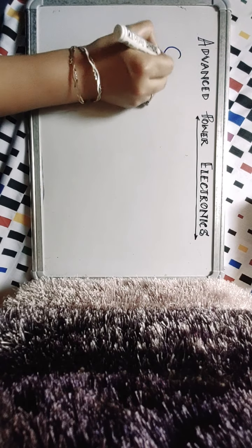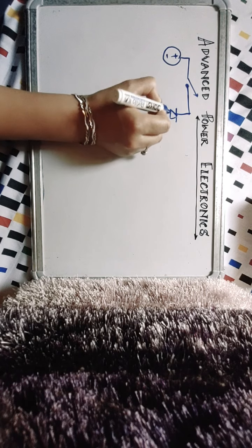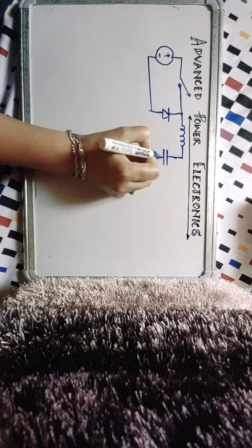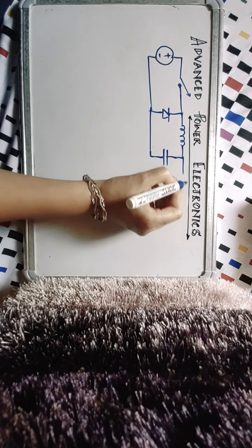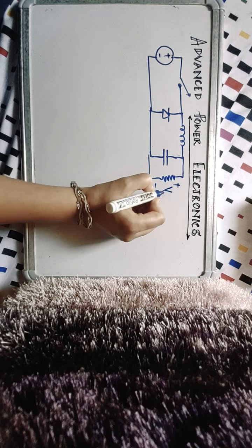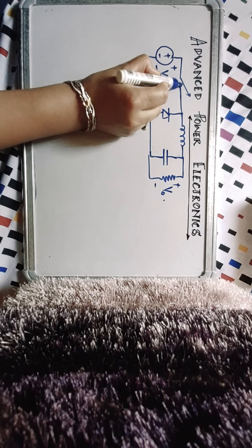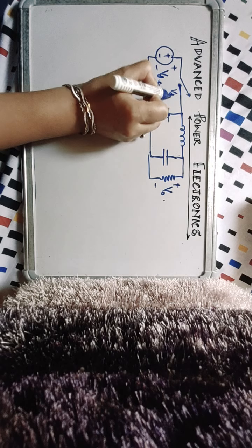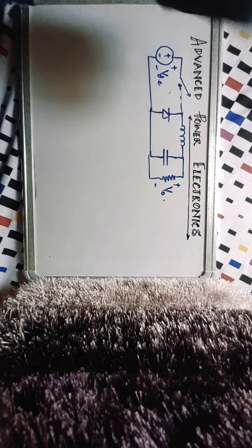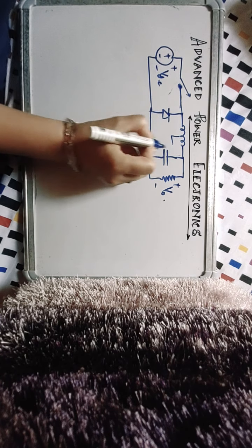So your buck converter has two very interesting components. Generally, not necessarily always, but usually you have them when your applications are those of power supplies where you want a regulated output. That is your L and C. So you have a load. The load will be defined by the user, what load will be placed on your converter. The input is already decided. For the device, you have seen that you have to choose a rating, and that rating is equal to VDC. And the diode, the other device, that is also chosen to be at a rating of -VDC. So you can easily select your VDC and you can easily select your diode. Now how do you design this L and C?